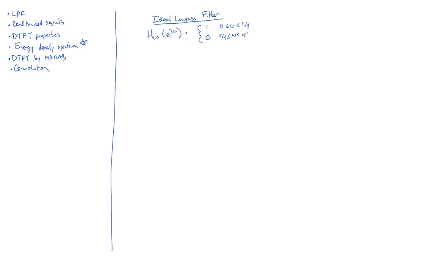Sir, what is the subscript for the H? Low pass, LP. So if we were to graph that, H low pass of e to the j omega, we're graphing here the DTFT. It would look like passing low frequencies with the value of 1, and then instantly stopping right here. Depending upon your sampling frequency, that would correspond to, say, a low-pass filter that would pass all frequencies exactly less than, say, 500 hertz, and then at 501 hertz, it would instantly stop it, up to its highest frequency, which was 1,000 hertz.